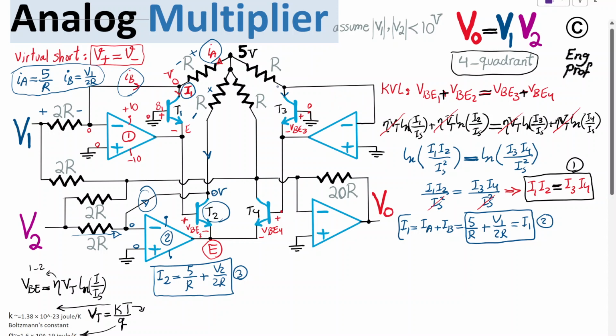So the only current that is coming in this case is just purely this current, which is, as you can see, if this op-amp 3 is also properly biased, so it has plus 10 volt, let's say, and minus 10 volt as an example, so its linear region of operation, virtual short, is going to be valid, and that means positive and negative input terminal should have the same voltage. You can see that positive terminal connected to ground, so it's at 0 volt nominal.